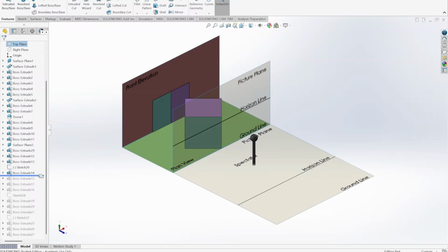So the first thing we need is to identify what's called our vanishing parallels, which are lines that go from the spectator up to the picture plane and then down to the horizon line. The way to find our vanishing parallels is by drawing a line parallel to the outer surfaces of the object closest to the spectator. So bring them parallel from the spectator up to the picture plane, and then down to the horizon line.